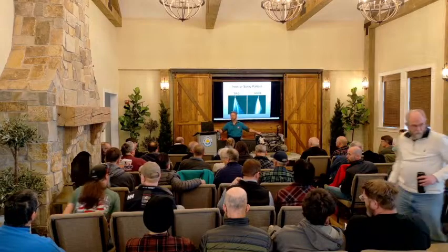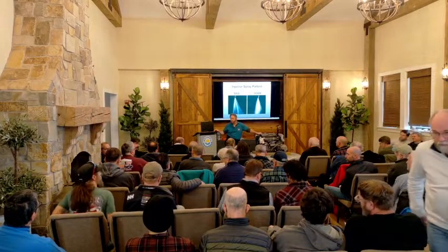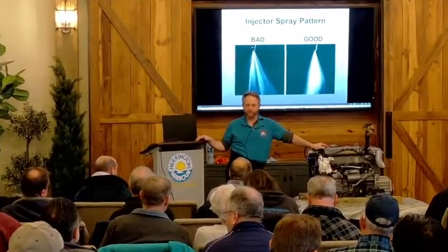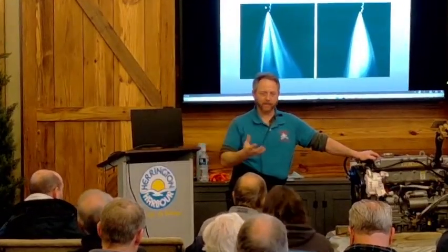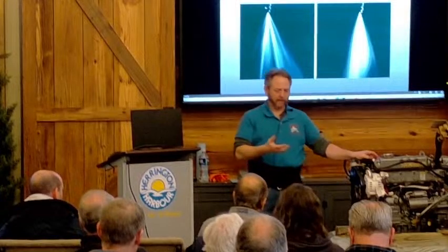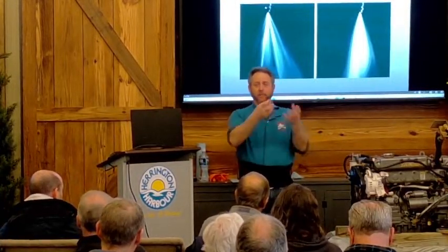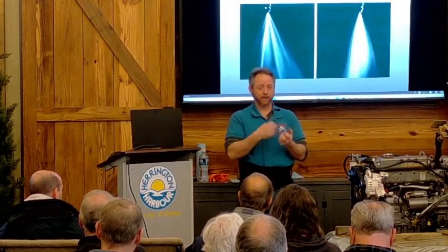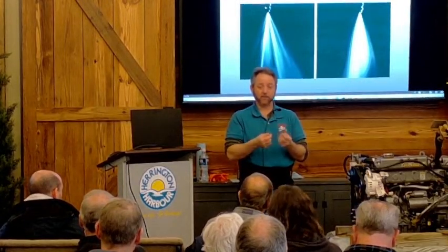On the subject, you recommend changing oil hot or cold? Definitely hot. The hotter the better. Getting the oil hot does a few things for you. One is it suspends the contaminants up in the oil, so when you go to pull it out, you pull more of the contaminants out. Secondly, it makes the oil less viscous, so it's thinner and it pumps out quicker.